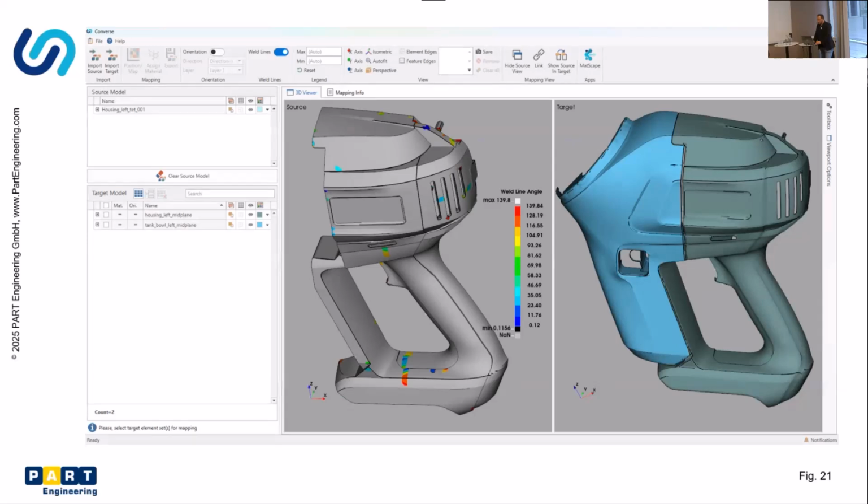This also can be mapped. And if you map it, you can even consider the different angles, of course. So in one weld line, you need not have just one angle, but different ones. So if you want to really consider a varying reduction factor, then you need to consider the different angles at the different weld lines. And therefore, of course, a mapping would be needed.